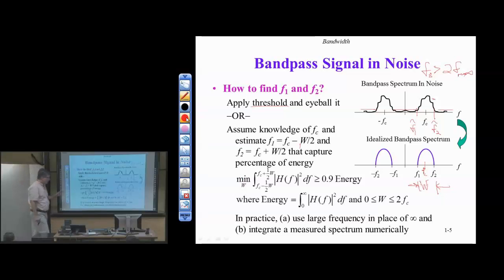Now, there's a limitation on capital W which we didn't see before. Because if I make W too large, I eventually get to the point where I occupy from 0 to 2 times capital W. So any solution of capital W that causes this right cluster of frequency content to be wider than 0, or actually the left edge goes negative, doesn't make any sense.